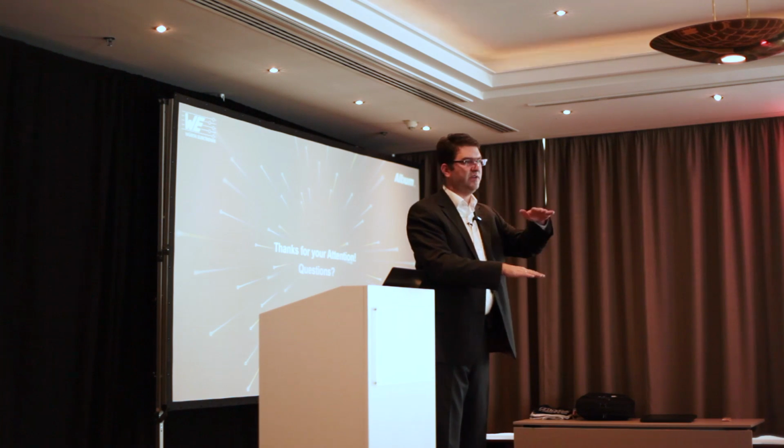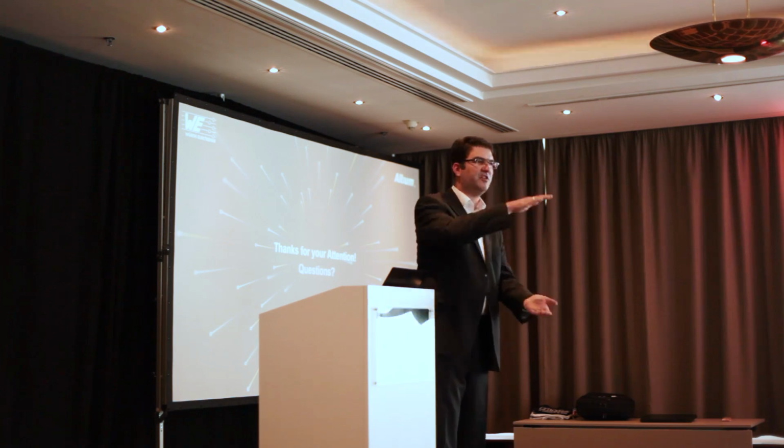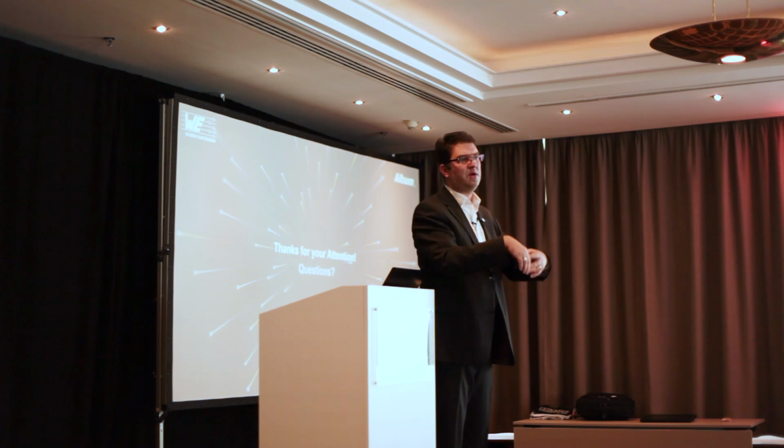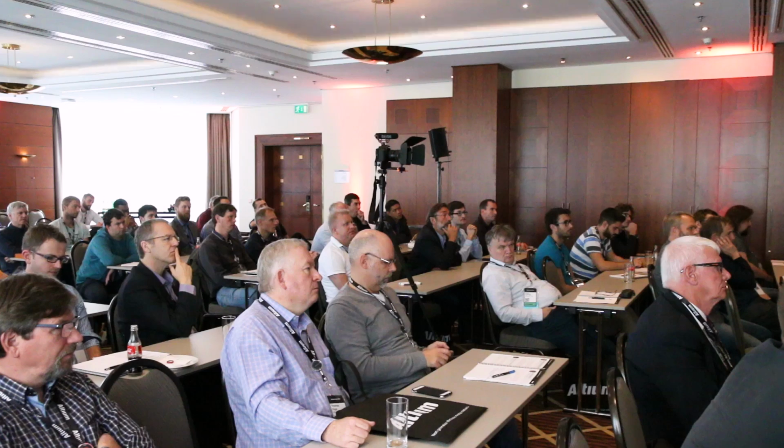We can stack prepregs, for example. So if there are 5 prepregs we need to cut out, we can stack them and cut them out all in one. Either we route them, or in higher volumes we punch them. So it's not one prepreg after another. But that's basically all the additional cost.